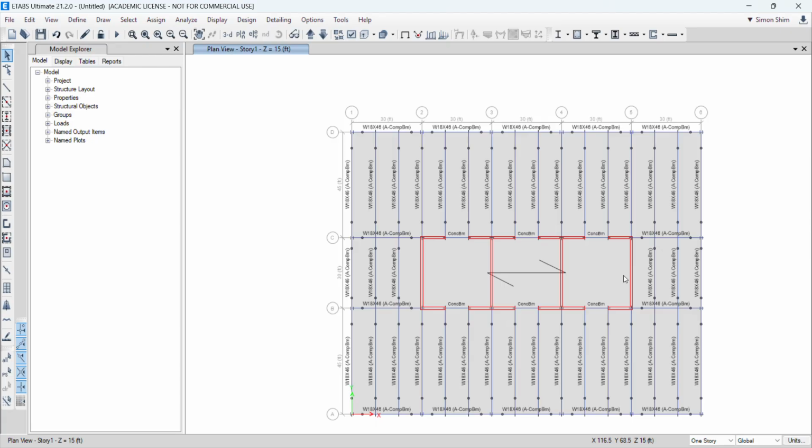So this is the general model. Inside the slab, we're most likely going to end up with a concrete gravity frame beam, and we're not going to pay attention here. Inside this concrete wall, it is likely concrete construction, a concrete slab and concrete beam inside. But we're going to focus on the composite beam framing outside.